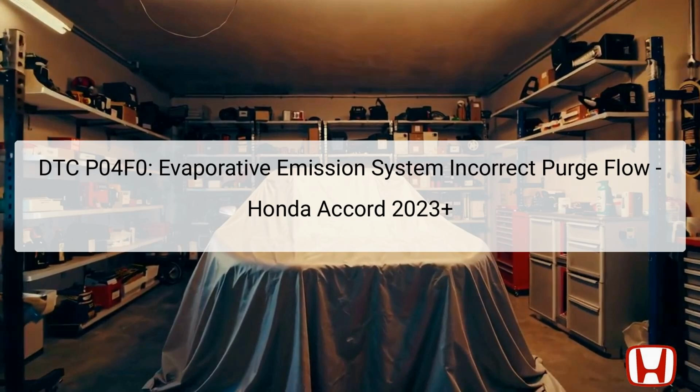When the PCM identifies discrepancies in the purge flow, it triggers the DTC to assist in diagnosing the issue. This problem is often linked to components like the EVAP canister purge valve, purge lines, and associated sensors. Diagnosing this code will involve inspecting these components using specialized diagnostic tools, such as the vacuum pump and pressure gauge, to ensure proper functionality of the EVAP system.